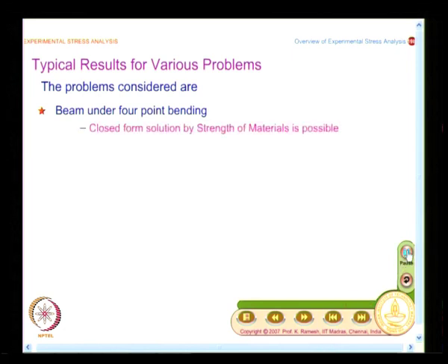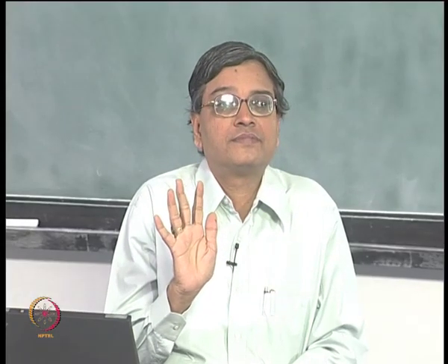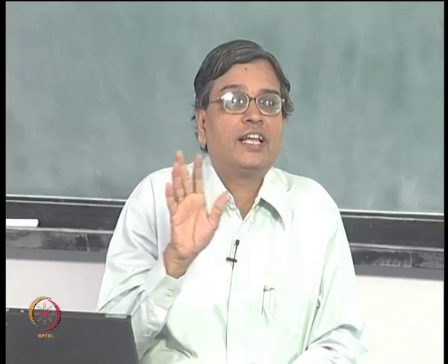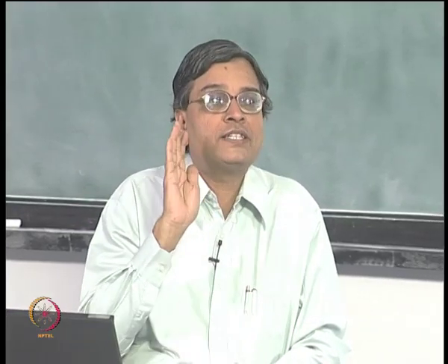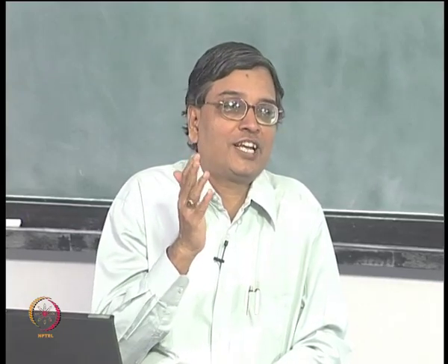and they are also done with a graded level of complexity. So, one of the simplest problems which I have taken is beam under 4-point bending. That is the first problem to start with, and why I have taken this is, you have closed form solution by strength of materials. So, that is what you have done in a course in strength of materials. So, you know completely the story of beam, leaving the points of loading regions away from it, you know what happens in beam, and I am sure you would have just looked at stress field. I do not think you might have looked at strain field or displacement field, we would see all that.